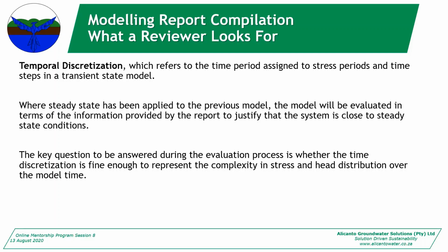So what that means is that if you have daily variations in a certain stress, like your abstraction, if you have it where you're pumping 1,000 cubes an hour on one day, and then 10,000 the next day and 5,000 the next day, then your stress periods are sort of a day long. But if you have a consistent pumping rate over every day of every month, you can use monthly time steps or even 6 monthly where you change your recharge conditions or anything like that.